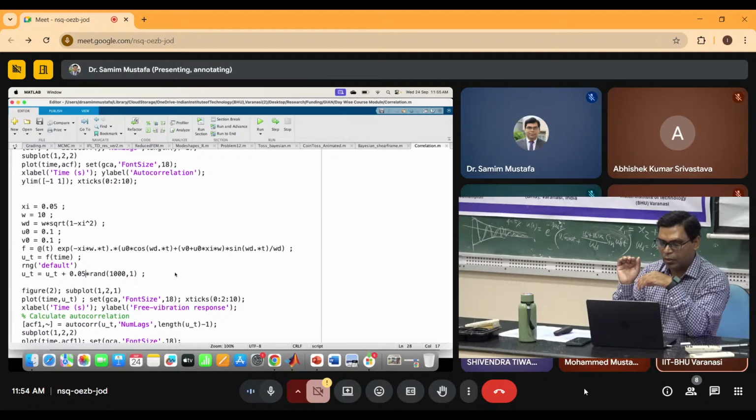So that's why I have demonstrated this by applying the autocorrelation to the entire signal. But your process would be, first you remove the noise from the signal, then you check whether the noise that is there is correlated or uncorrelated. Based on that, you develop a mathematical framework to model that noise. If it is uncorrelated, then you have to assume an uncorrelated noise mathematical model. If it is correlated, then you cannot assume that it is simply uncorrelated and the other parts are kind of zero, right? So this cannot be done. So this is one of the examples that you can do.